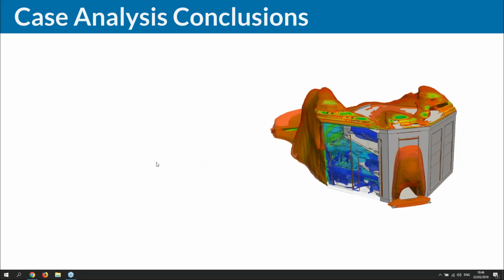And Bhav wants to know if the ASHRAE code data and tables are input in SimScale. Not really, it depends. Usually you get some of your boundary conditions from the ASHRAE standards or the other codes, and then you use the simulation result as the input for the standard calculation. But there are a lot of different possibilities. You can use them together hand in hand, but you can also use simulation sometimes as an alternative.